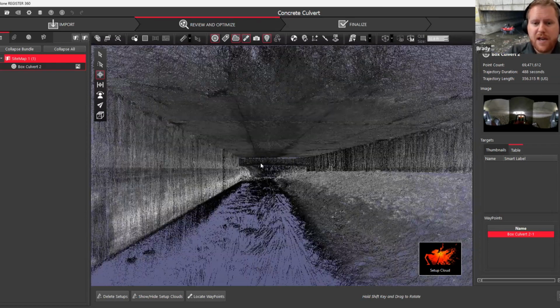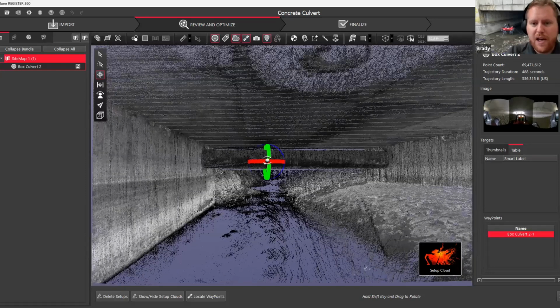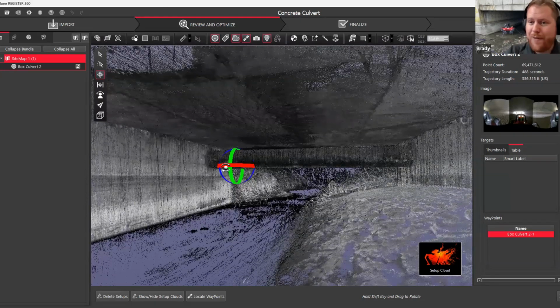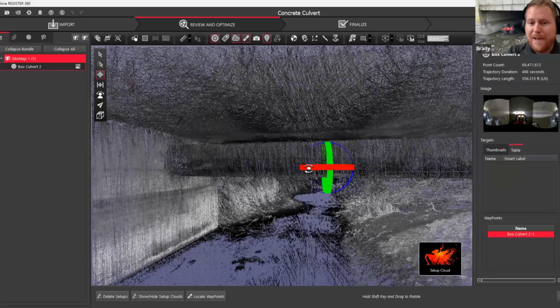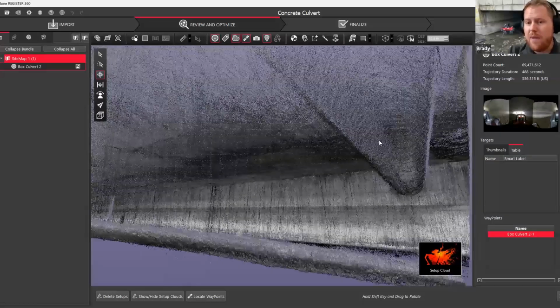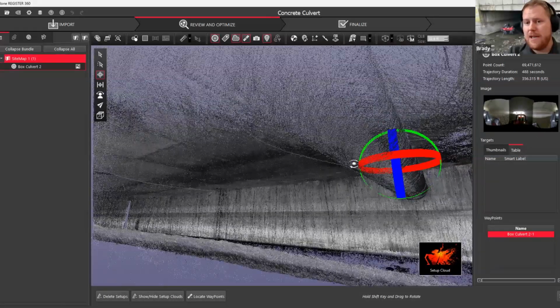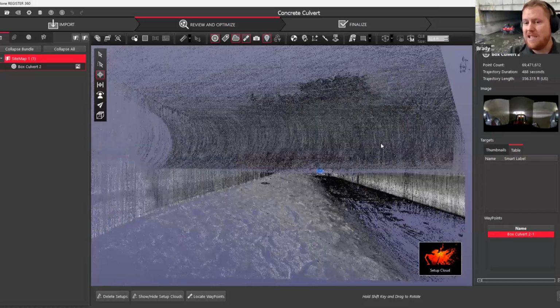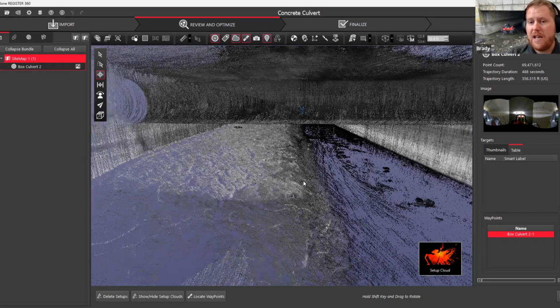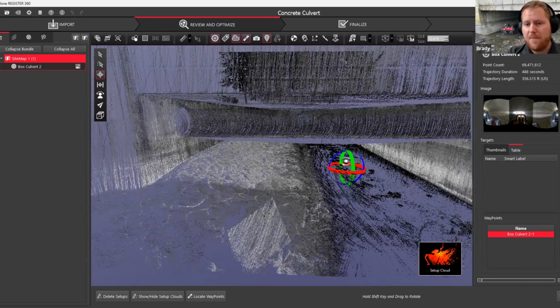As we go to this other side here, I also want to point out we also have another pipe that is running perpendicular through this culvert itself. I don't know if this is freshwater. I am not sure, but we've gathered information to verify that this pipe itself is not deformed. It's not going at a weird angle. It is exactly where it needs to be. We don't see any stress line fractures or hairline cracks, which means that we don't have any contamination between these two sources of likely water that's going through this pipe as well.